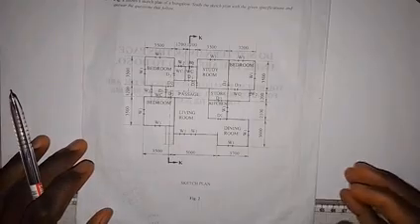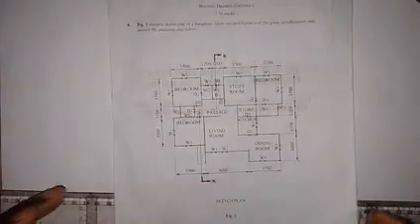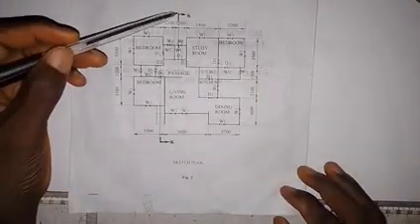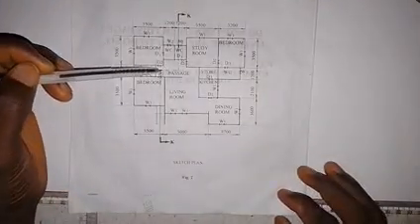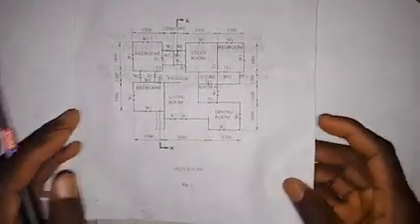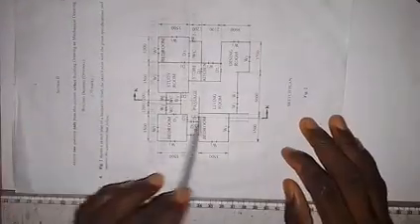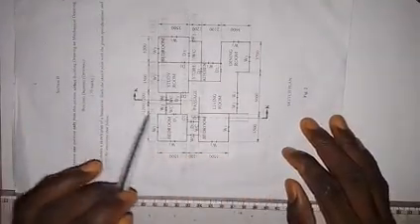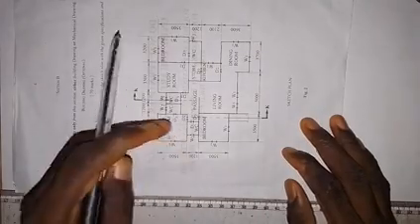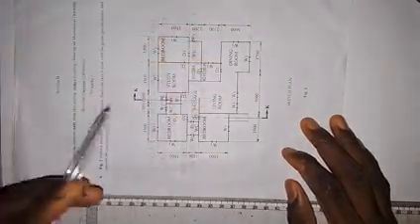And so, as we are asked on this page, we are to draw to a scale of 1:50 the view of section KK. On the sketch plan, this is cutting plane KK as it goes like this. If I turn it like this, this is the direction of the arrows. If we cut this part off, we want to see what we have left on this part.